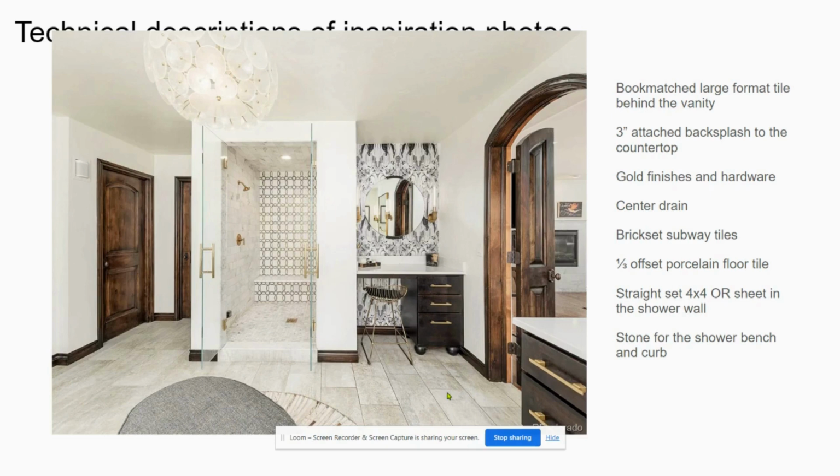And when you are making your work order for your installer, you'll need to put all of those descriptions. So you would need to tell them if it's a third offset brick set or half offset. With wood planks, you would do stagger the end joints as the install pattern. And in the fundamentals or construction docs, I can't remember, but in those 2 classes, there is a worksheet that has all of the install patterns and their names on it.